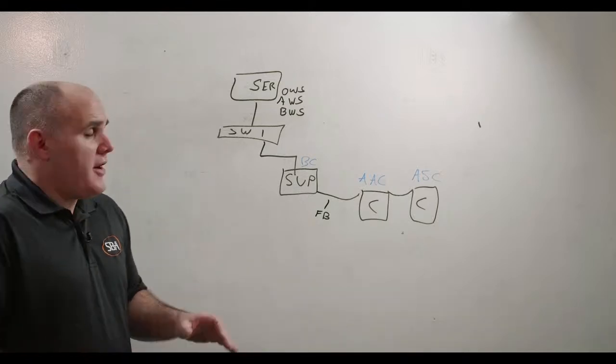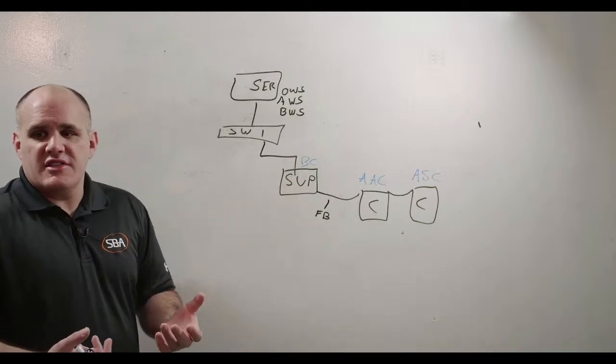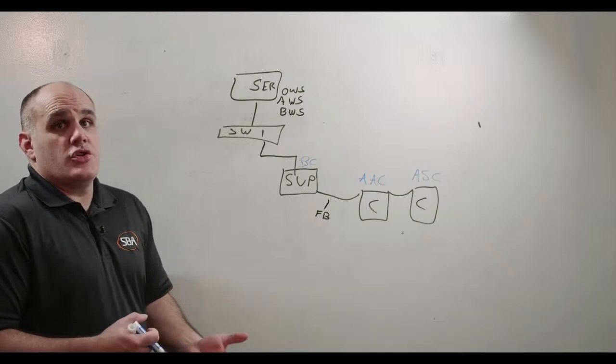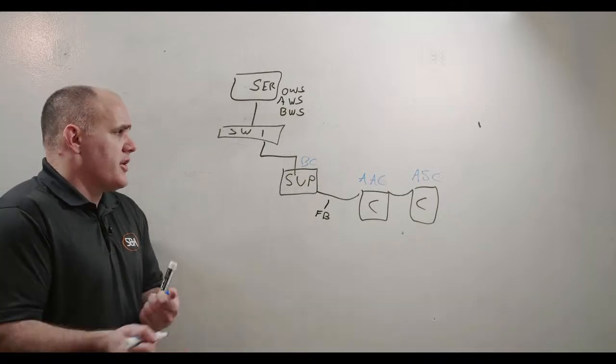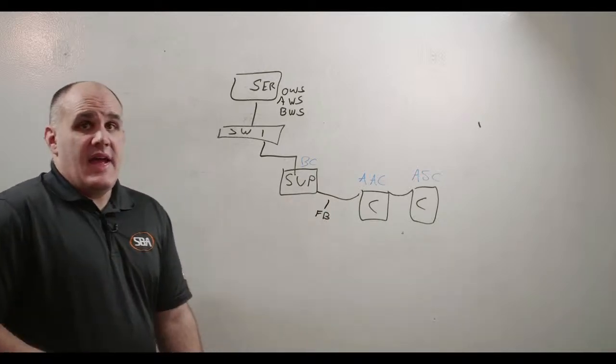Now let's talk about micro architectures, which are 3-tier architectures, and there's really 2 types. There's an IP microarchitecture and a non-IP microarchitecture. Now, a non-IP microarchitecture would simply be the supervisory device and the field controller and the I/O.